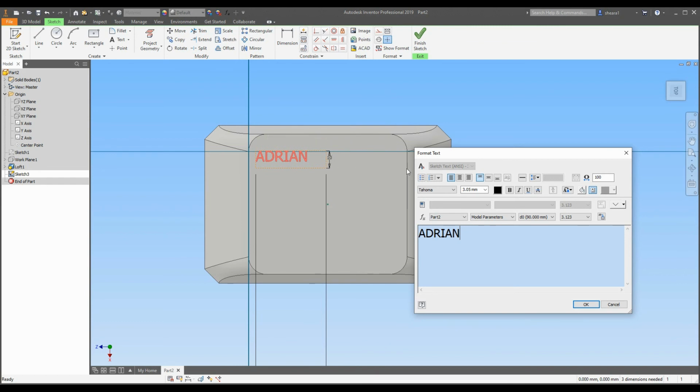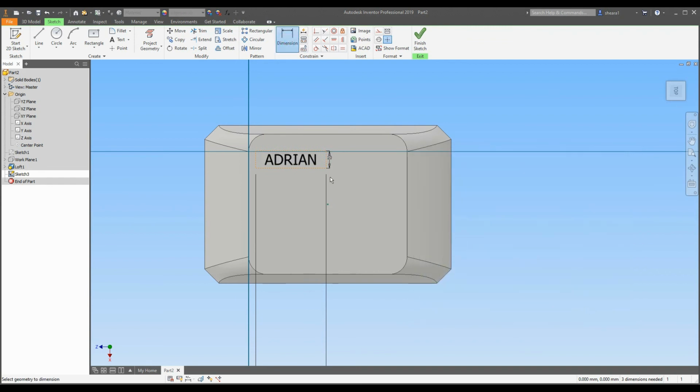The same thing with the sides. But the text that's in the box is sort of out of place, right? We can easily fix that by making it center justified, by clicking the middle justification and the center justification buttons up here. Click OK. It'll justify itself. Bam.